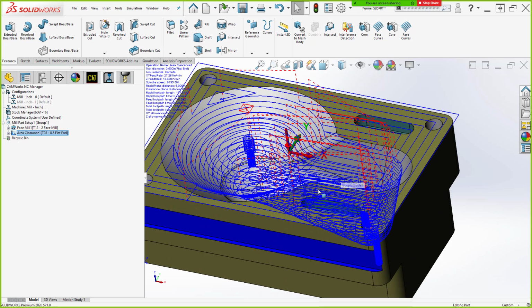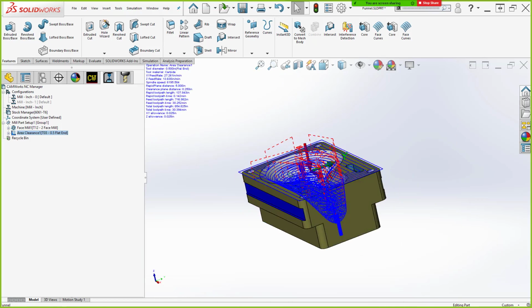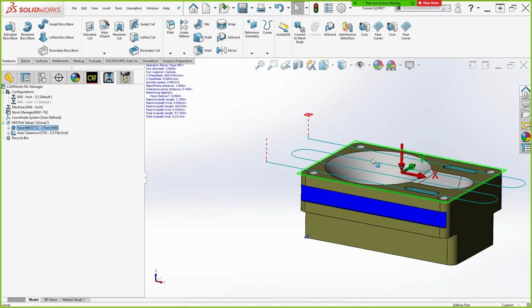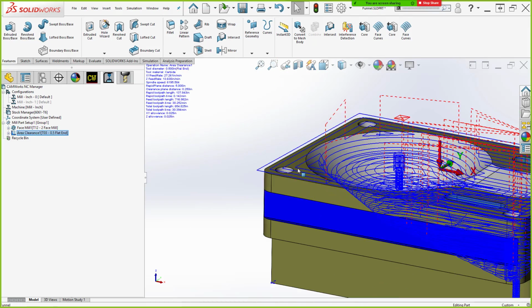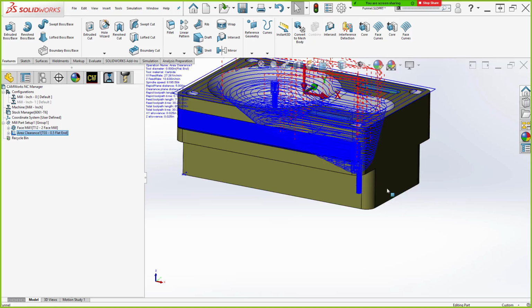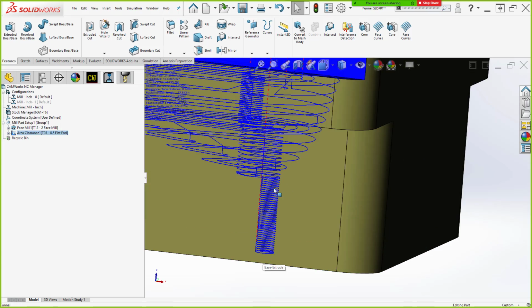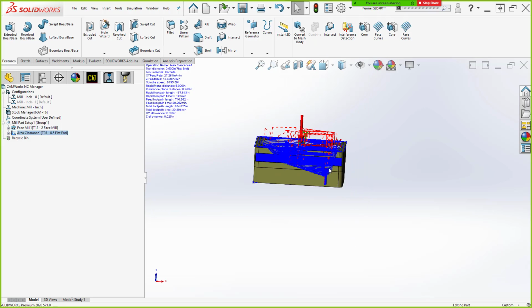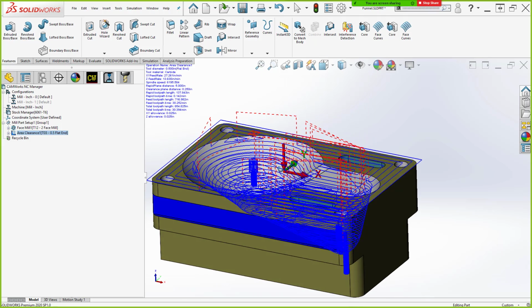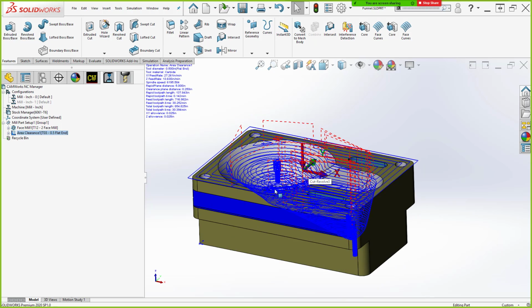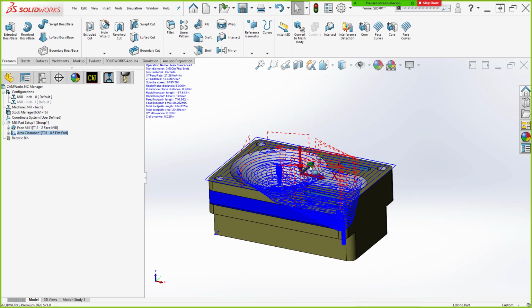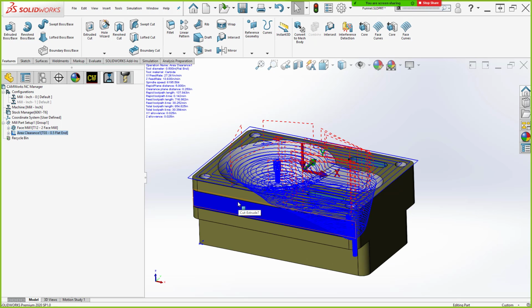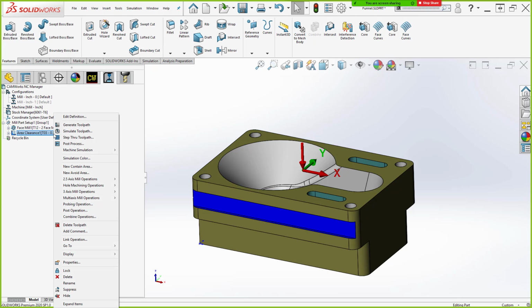So when I look at this area clearance, it's doing all displayed. I already have a face mill up top, right? I don't need this area clearance to machine the material up top. I'm also not thrilled about it going down into this hole at the bottom of my part here. I'd probably rather drill that later than interpolate it with this flat end mill. So there's a couple ways we can deal with this. Like I mentioned, there's quick ways and there's inefficient ways.